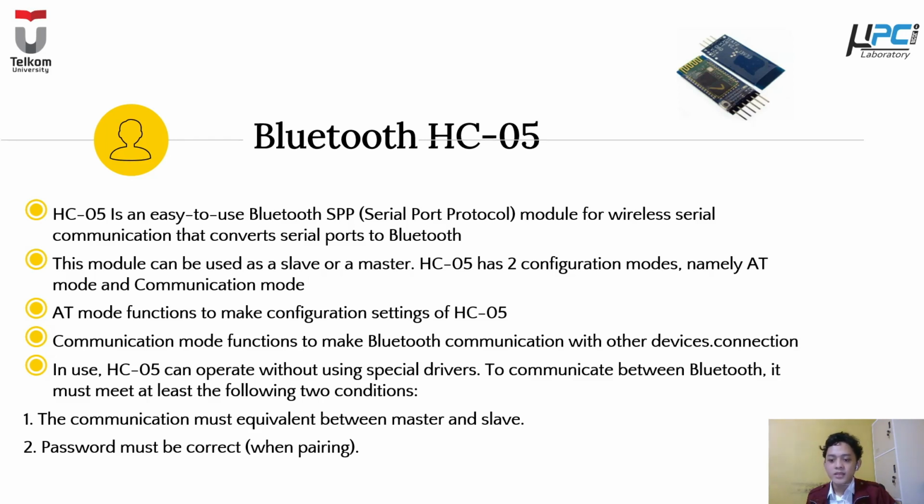HC05 can operate without using special drivers to communicate via Bluetooth. It must meet at least the following two conditions. The first condition, the communication settings must be equivalent between master and slave. And the second, the password must be correct when pairing.